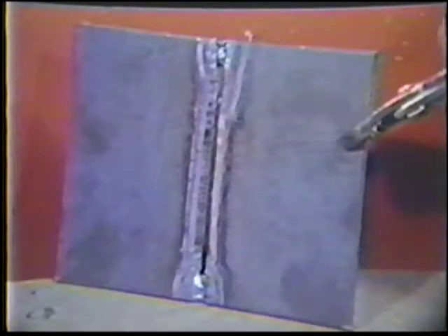Over a certain thickness, about 3/16 inch, it is necessary to bevel the edges of the joint. Using a larger tip alone is not the solution for obtaining full penetration. The material would merely overheat. Similar conditions apply to fillet welds. Joint design must be carefully considered to produce the desired strength or condition of the weld.